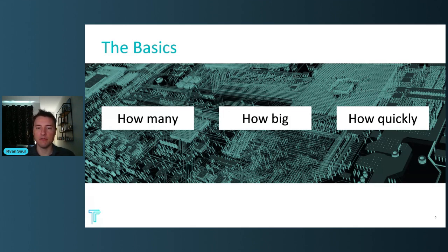So if you don't feel comfortable estimating how many of your boards will fit in one production fab panel, I would reach out to your supplier. Oftentimes we can give you some rules of thumb about how much of the fab panel is usable, and if you have a specific design already or specific dimensions, they can give you a direct answer on what quantity will fill the fab panel. All right. Okay, so that's the basics. Let's keep moving.